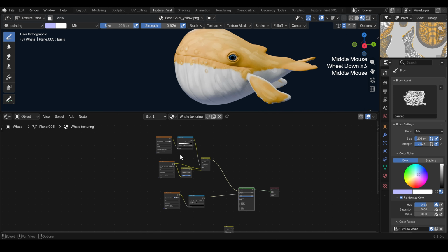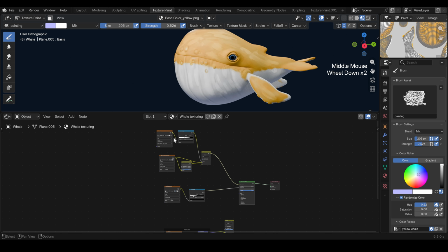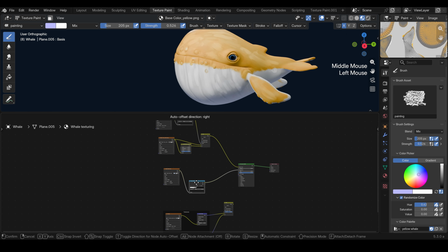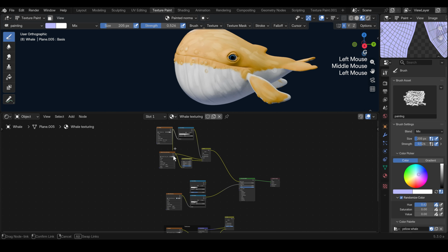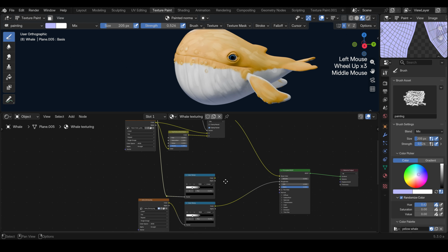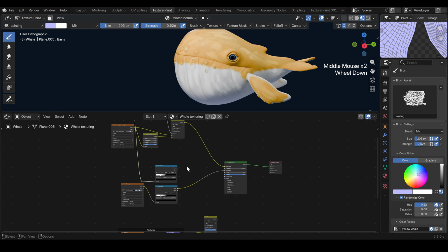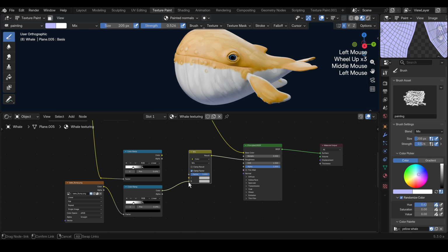So now that we have this stuff here, let's also create the roughness variations. For this, we're gonna use this normal map again, and I think we could even avoid duplicating it. So let's simply create a duplicate copy of the color ramp again, and since this is pretty close, we can just shift right click and add a little dot, like so. So it looks a bit less confusing.